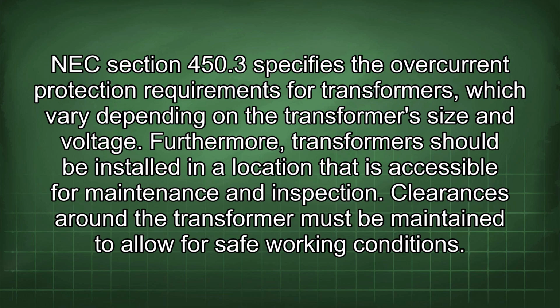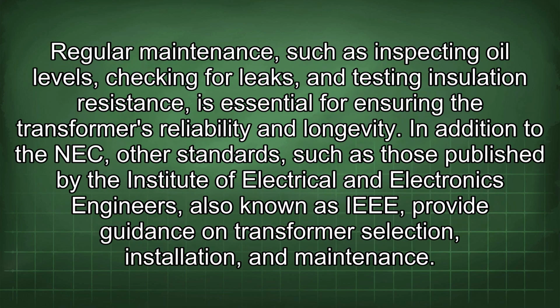Furthermore, transformers should be installed in a location that is accessible for maintenance and inspection. Clearances around the transformer must be maintained to allow for safe working conditions. Regular maintenance, such as inspecting oil levels, checking for leaks, and testing insulation resistance, is essential for ensuring the transformer's reliability and longevity.